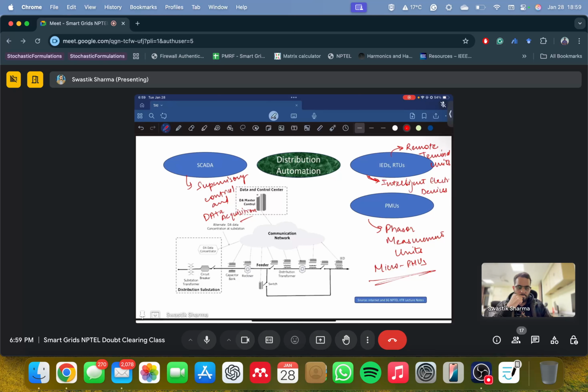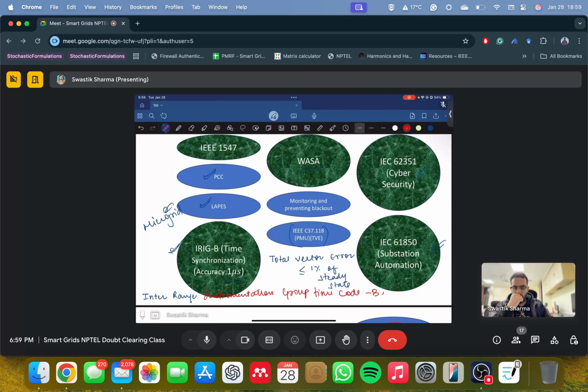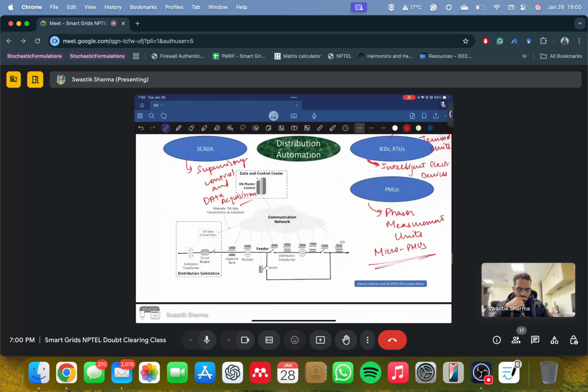They do transmit information on the IEC 61850 protocol, the substation automation. There are differential protection relays which transmit information over hundreds of kilometers for transmission lines. So the PMU application, as I understand it, is very specific to voltage and phase angle measurements, for monitoring purposes. That's my view. I'm still exploring this.